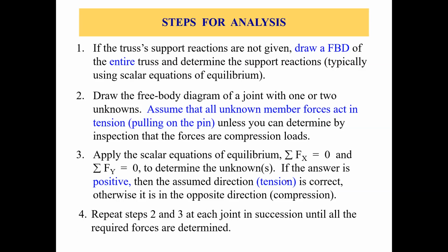Repeat steps 2 and 3 at each joint until all the required forces are determined. So you start from one joint and then keep solving other joints until you know all the member forces, because that's the result which you want. After you know all the forces, the analysis is done. So these are the steps you need to follow for the force analysis of a truss system by the method of joints.